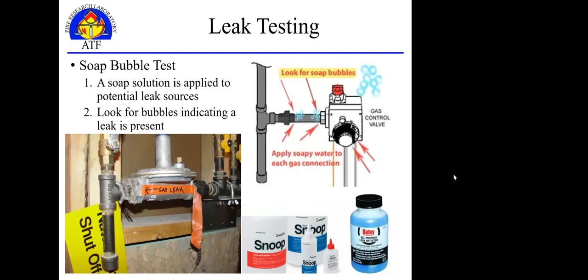Soap bubble tests, just like it sounds. I'm putting some sort of solution that generates bubbles when there's some sort of leak and air flows through it. If I find bubbles, that means I've got a leak. If I don't find bubbles, that's a good thing.